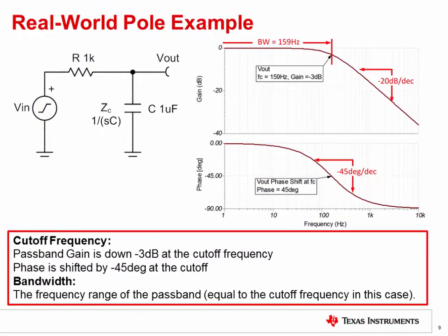The objective of this circuit is to pass low-frequency signals and stop high-frequency signals. For this reason, the pole frequency is often called the cutoff frequency and denoted by Fc. The idea is that all signals with frequency greater than the cutoff frequency are cut off or eliminated. In fact, the high-frequency signals are only attenuated and not fully eliminated. Another term associated with a low-pass filter is bandwidth. Bandwidth is simply the width of the passband, and in this case is synonymous with the cutoff frequency.